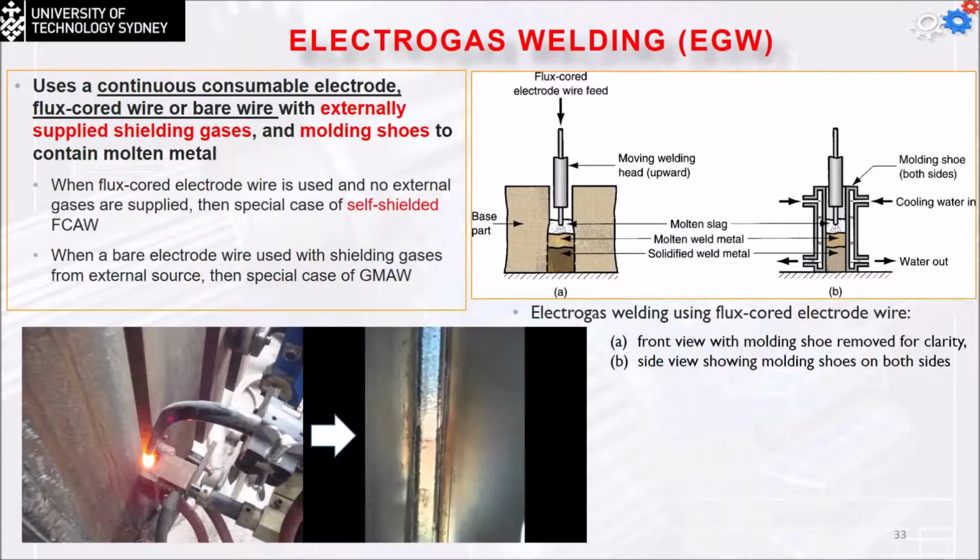This is a cross section of the work. So actually we're melting the filler, and it's going to start to solidify at the base and upward. This shoe is going to be on this direction and the other side, as we can see here. So it's going to fill the gap between the two metals and solidify. To speed up the solidification, we're usually running water through something like a heat exchanger. The shoe actually is a heat exchanger. So the water is going to absorb the heat from the molten metal and make it solidify at a faster rate.